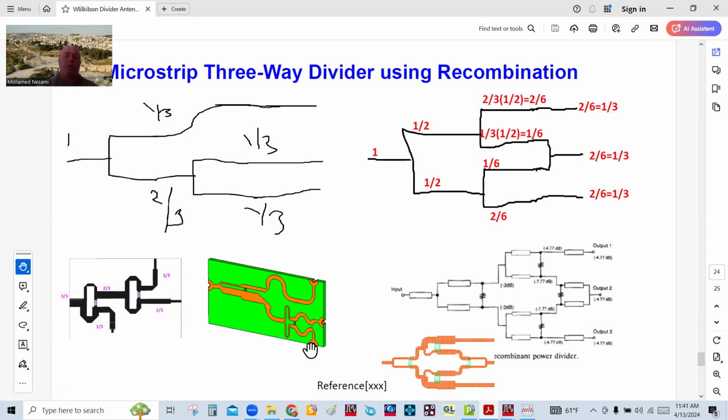And that's very important for phased array antennas, because that could distort. If there are any mismatches in the paths in here, path lengths, you end up with distortion of the beam, and we don't want that. Now, if you're doing beamforming, of course you can always correct for that in the beamformer states. That's another issue that I forgot to mention. Now we're really tapering, so we're really putting a weight on every element in the array. This is really what it is. It's a fixed, static, one-state beamforming essentially, but we're doing it with just amplitude weights. We're not messing with the phase.